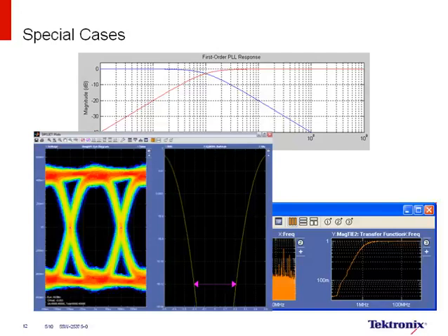The net result here is that in a clock data recovery system, the PLL inside will track and reject low-frequency jitter, hence the jitter transfer function is low, and what it is not able to do is track and reject high-frequency jitter, so the jitter is passed through. So that's why it's critical, as I mentioned earlier, to be able to understand what the loop bandwidth is, because it determines what jitter frequencies are tracked and what jitter frequencies are rejected.